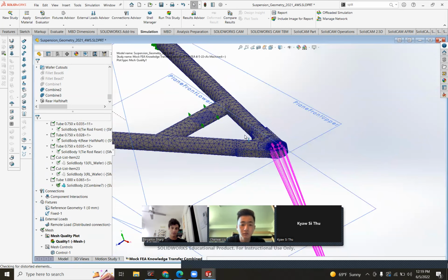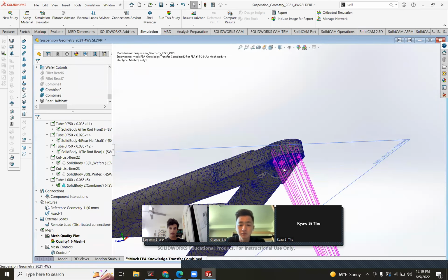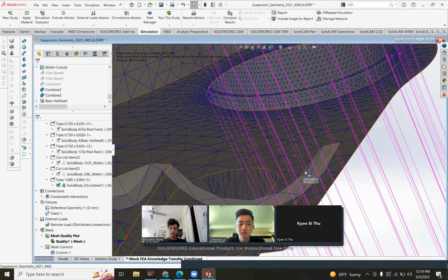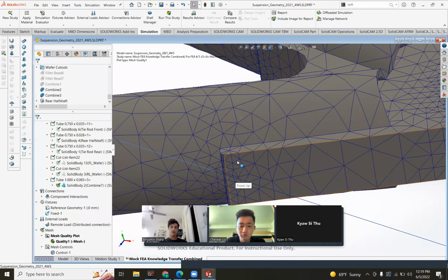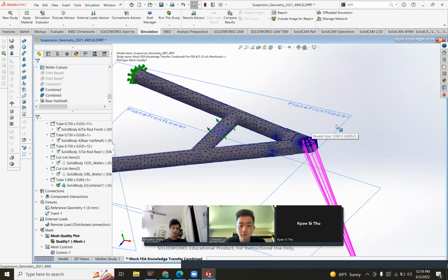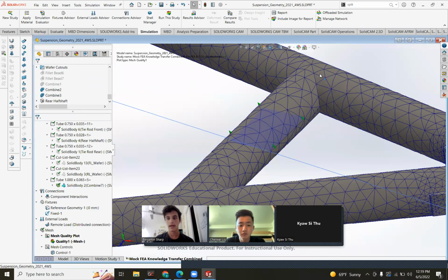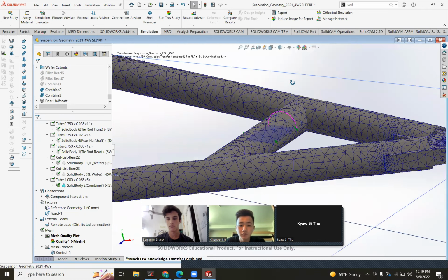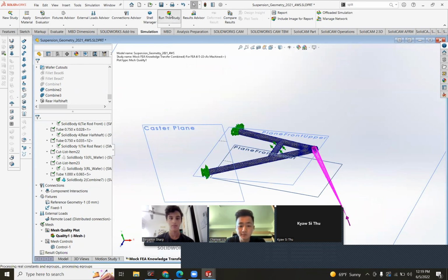Wow. That looks pretty good. So we have a super fine mesh now here in the bearing cup. Great. It automatically did a finer mesh around the tight curve. That's why I chose a curvature based mesh. And it mapped this pretty well. Okay. Reasonable. Let's try this. I'm hopeful this could work.